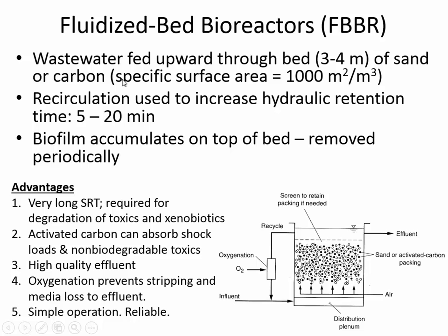Finally, in the case of a fluidized bed reactor, you have particles that, if you didn't inject air, would settle downward, but because you're injecting air, these particles stay suspended, and they allow a slime layer to grow at the top of the surface here. It's a biofilm that accumulates on the top of the bed, and so it's just kind of a unique way of not having to use a clarifier all the time.